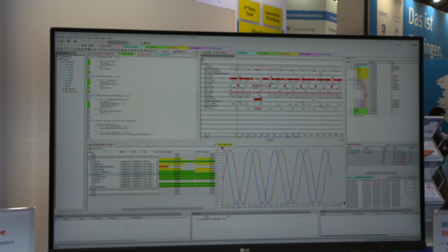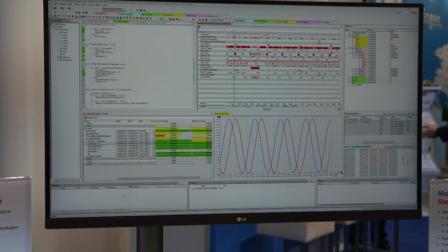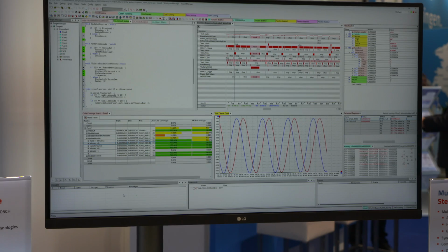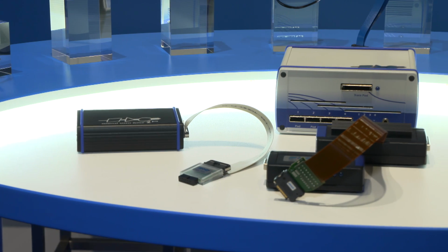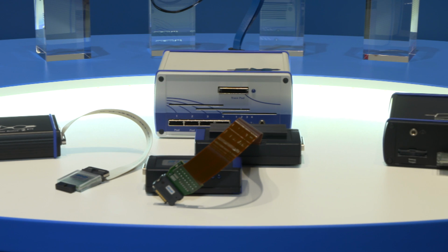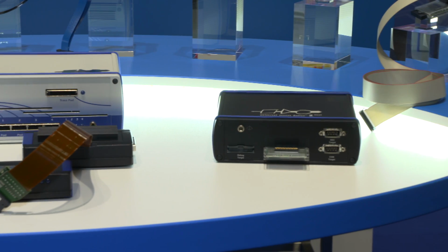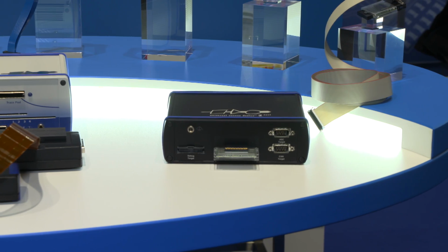And then we have, of course, a focus on trace. That means using non-intrusive methods to get the runtime behavior of the system into the tool to analyze the timing, for example. For that, we have also our hardware support, our Universal Access Device family with extensions for trace, like our high-end device, the Serial TracePod 100G, that allows you to observe the runtime behavior with a bandwidth of up to 100 gigabit per second for recording the trace information.